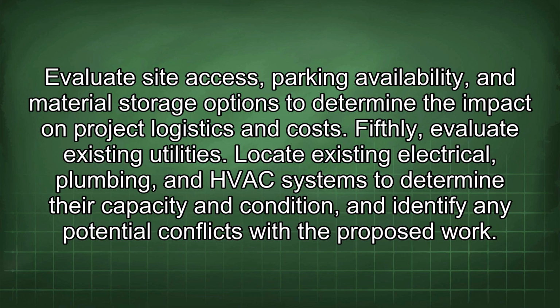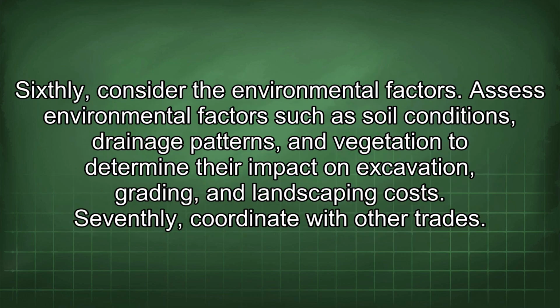Fifthly, evaluate existing utilities. Locate existing electrical, plumbing, and HVAC systems to determine their capacity and condition and identify any potential conflicts with the proposed work. Sixthly, consider the environmental factors. Assess environmental factors such as soil conditions, drainage patterns, and vegetation to determine their impact on excavation, grading, and landscaping costs. Seventhly, coordinate with other trades.